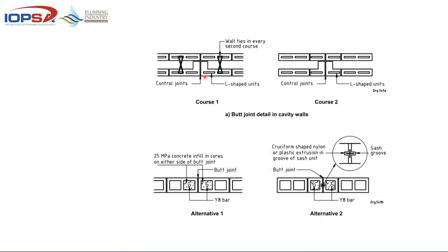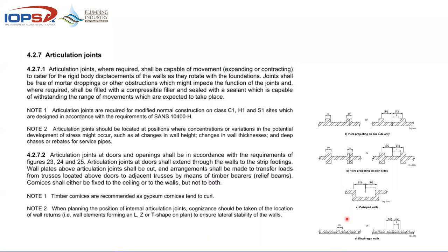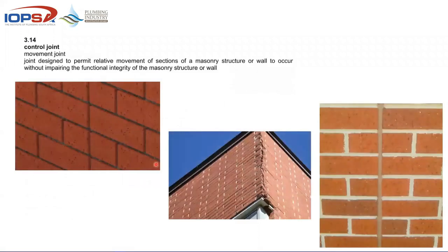So when you're looking at walls, especially longer ones, the builder would be forced to provide joints. You get different types, columns, thicknesses, even blocks. There's a detail for most of these things here, but there's a pipe joint there with reinforcing. So there's allowance made for specific movement on all of these different shapes and angles. And there's a typical example of a very nice movement there.